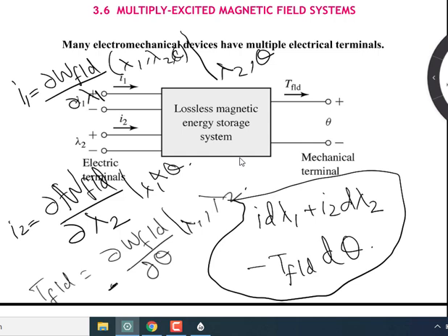So if we try to have a relation between bank balance and expenditure while keeping the income constant, then obviously they will vary in opposition. If your expenditure increases, then your bank balance will decrease. The same thing is true for torque or force with stored magnetic energy. That is why all the time we need to incorporate that negative sign, to ensure we corroborate with the understanding of energy conservation, right?